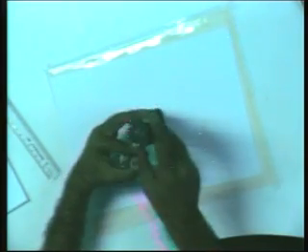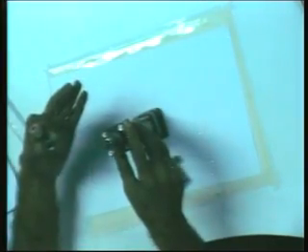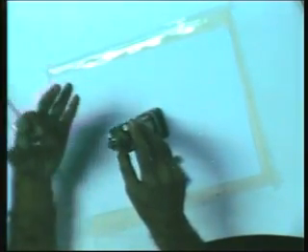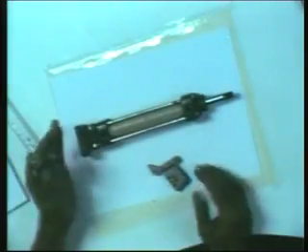So that is the advantage of what you call the hydraulic system. You could use oil, you have special oils, sometimes even water can be used. Any liquid can be used, and liquids are incompressible. By controlling the valve, opening and closing it, you can put a motor on top, control this with a computer, open and close and control the velocity, the rate at which the oil flows. You can stop it anywhere. That is the advantage with the hydraulic actuator.